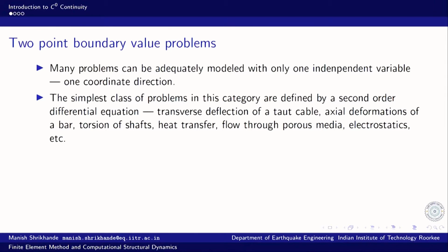The simplest class of this problem is defined by a second order differential equation, similar to what we had seen earlier regarding describing the axial deformation of a bar or a heat conduction in a rod, or it can also describe transverse deflection of a taut cable, or flow through porous media, or even electrostatics and several other problems.